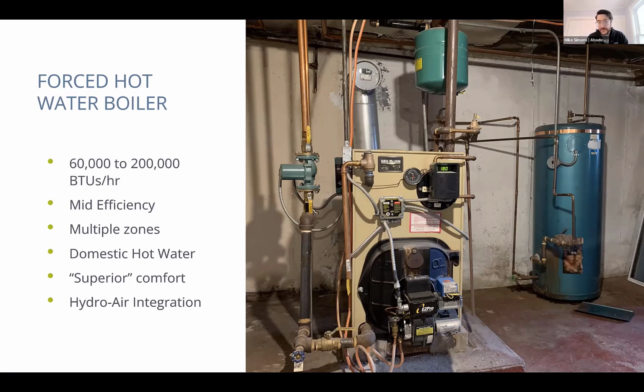The problem with this, and why I keep talking about 180 degrees, is that air to water heat pumps are real. However, they are looking to put out a water temperature between say 90 degrees and 140 degrees. And the closer you are to 90 degrees, the more efficient the equipment becomes.